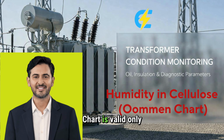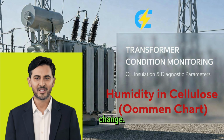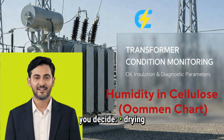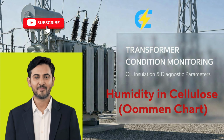The Oommen chart is valid only when the transformer is thermally stable, operating normally, and not under sudden load change. Used correctly, it helps you decide drying urgency, load limits, and insulation risk.